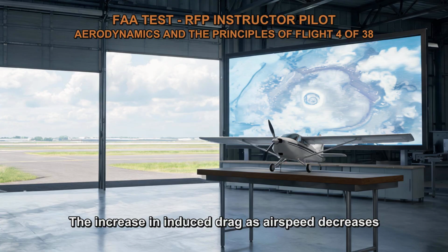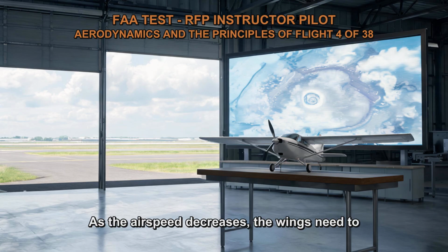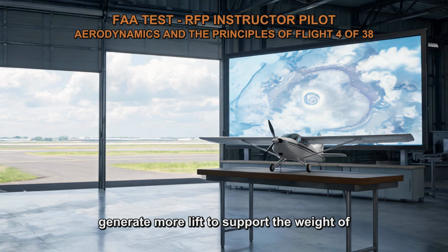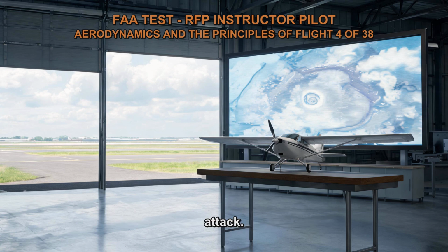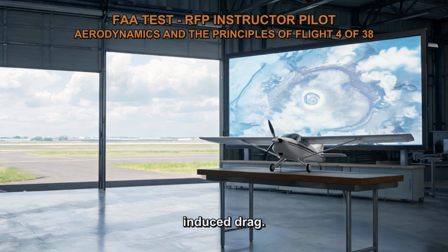The increase in induced drag as airspeed decreases is primarily due to the higher angle of attack required to maintain lift. As the airspeed decreases, the wings need to generate more lift to support the weight of the aircraft, resulting in a higher angle of attack. This higher angle of attack leads to increased induced drag.